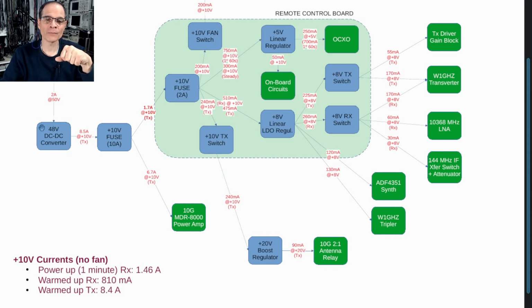This guy can run from 36 volts to 75 volts. So I will still put out our 10 volts up on the tower regardless of the voltage drop on the power supply uplink. So that, I think, is the best solution. And the efficiency of this guy at 10 volts with 48 volts is 90+%. So yes, it will dissipate some heat, but I think it's a better solution anyway.